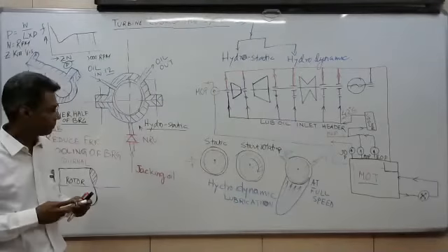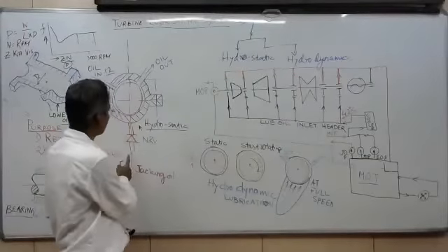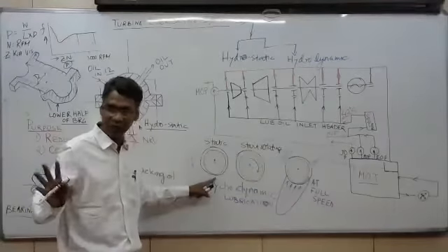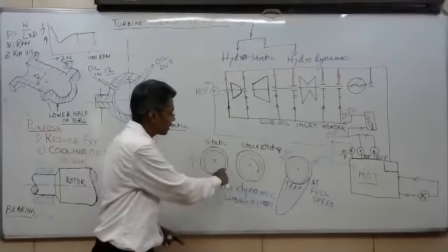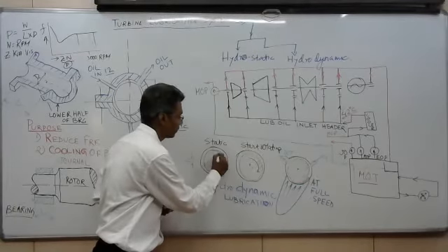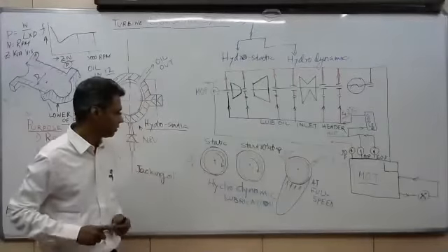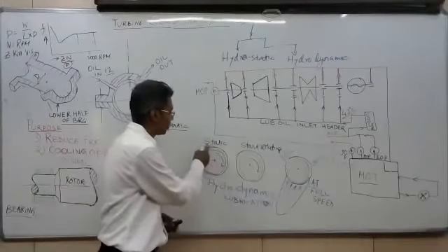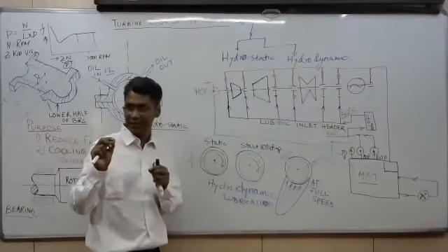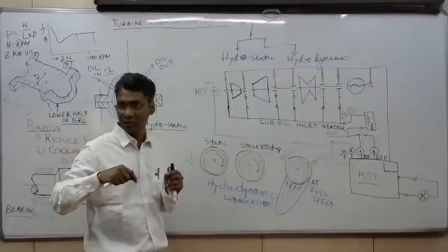So before starting, we are providing some oil below this surface. That is called static lubrication. Forget about it. Now slowly you start rolling the turbine in this direction. Now we are starting from 0 RPM. We are starting this rotor and this bearing has some clearance, a few millimeters of clearance, because we have to provide some oil space.